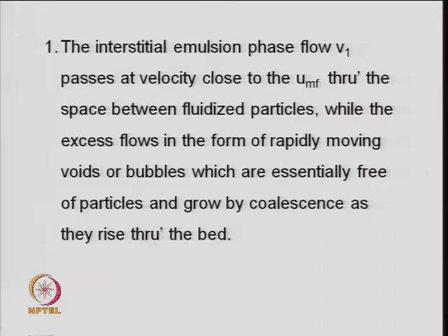So, more reaction is in the bubble phase, the cloud phase, because it has the solid and the gas. Rather, in the emulsion phase, the solids are more, and the gas is at almost 0 velocity there. So, this is one thing, that interstitial emulsion phase flow V1 is at velocity close to the minimum fluidization velocity through the space between the fluidized particles, while the excess flows in the form of rapidly moving voids or bubbles which are essentially free of particles, and grow by coalescence as they rise through the bed.